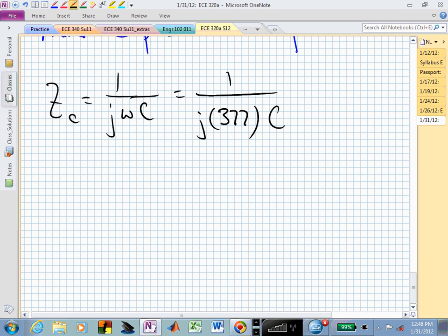That's the impedance, and what do we want, or what do we need? We need minus J57K. But do we need that from this, or what is supposed to be giving us the minus J57K? What are the units on that? Well, this is an impedance, but what we actually need is for this impedance to give us some reactive power, which is a little bit different than just the impedance. Yes?